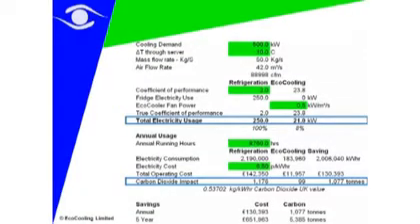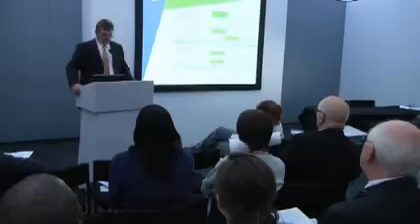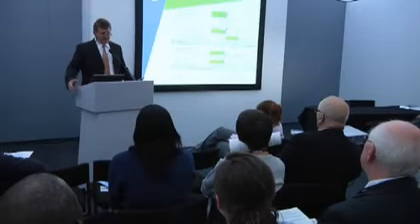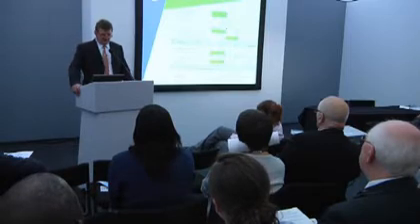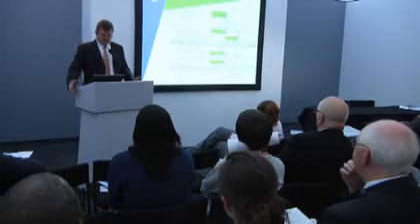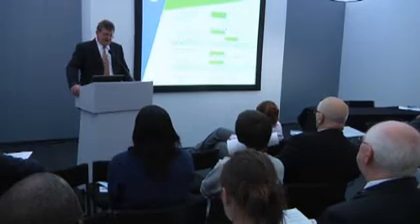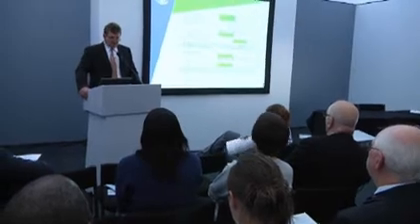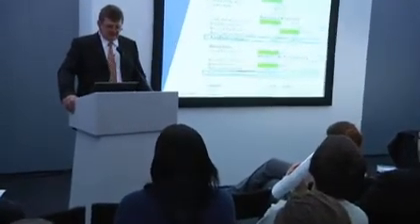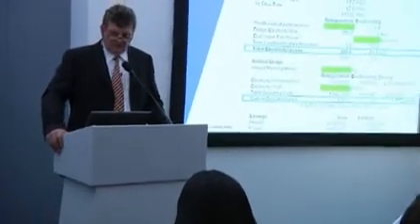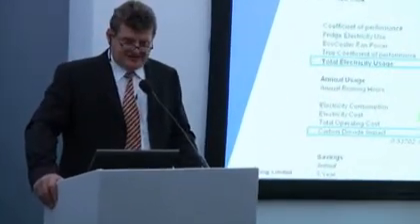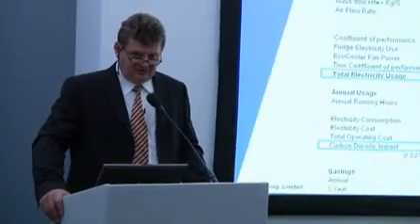The next stage of that spreadsheet, you will see there's a comparative cost, 2 columns between refrigeration and an eco-cooling CREC system. The coefficient of performance of refrigeration in a PUE 1.6 data center will be about 2. That means for the 500 kilowatts of IT load, we will be putting 250 kilowatts of energy continuously into the cooling system. The equivalent capacity of cooling delivered by an eco-cooling CREC system would only require 21 kilowatts of electricity. So you'd see 92% less energy put into that system.